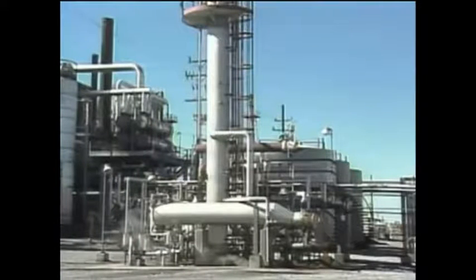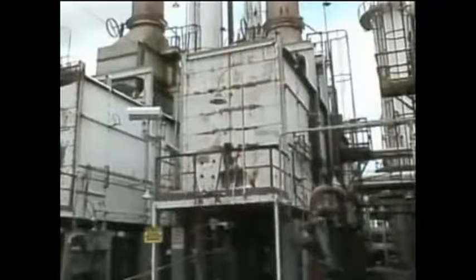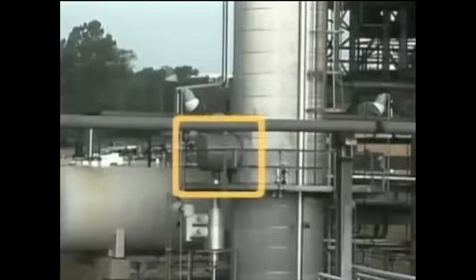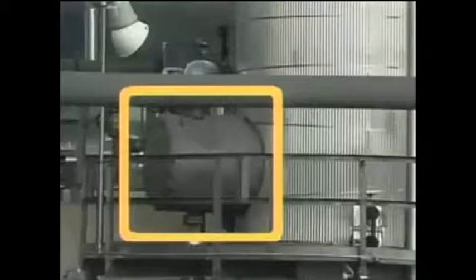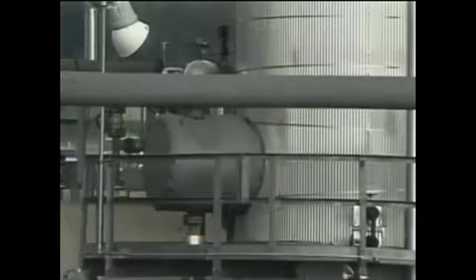In general, internal and external reboilers work in much the same way. Steam or another hot fluid is used as the heating medium, and the vapors or vapor-liquid mixture that is produced is used in the tower to provide heat for distillation. An important part of a distillation process is the overhead system, and one important piece of equipment in the overhead system is a condenser. A condenser in an overhead system is often referred to as an overhead condenser.